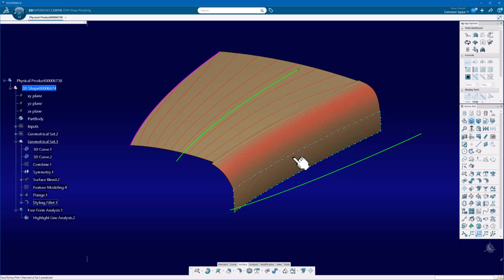Now, you can build like this very similarly inside of GSD, right? Generative Shape Design will allow you to build very similar to this, but the difference between here and GSD is I can control the amount of math on those surfaces. I have G3. I have those crowning features, the feature modeling, where I'm parametrically making modifications and so on and so forth.